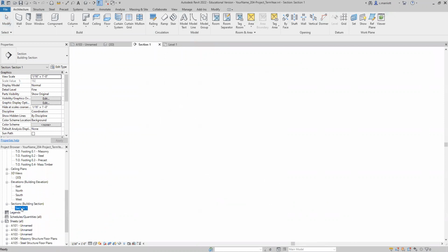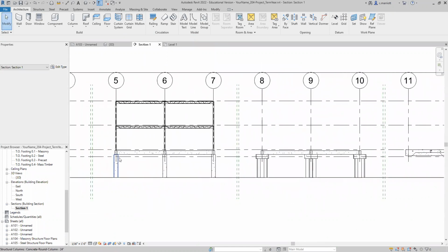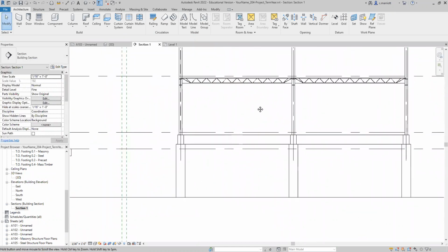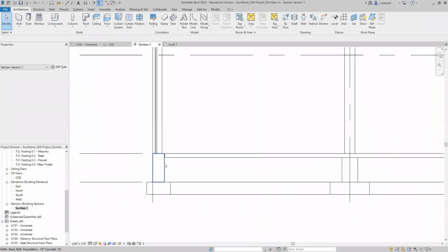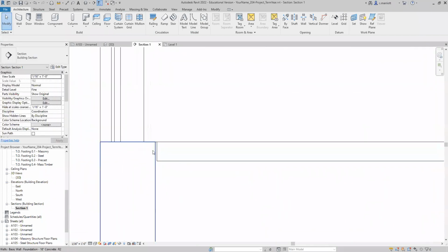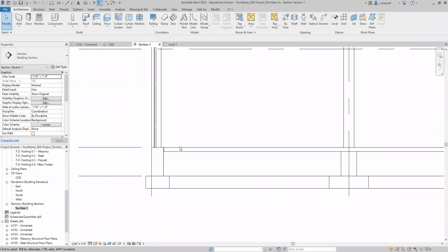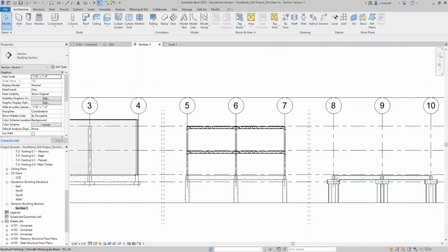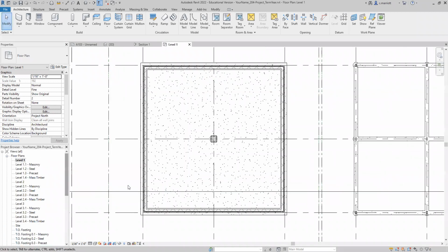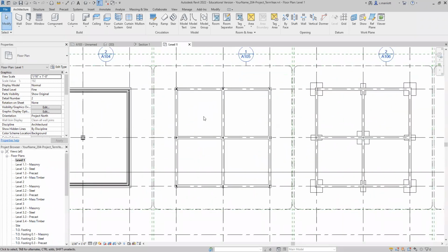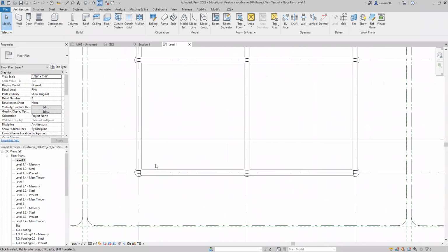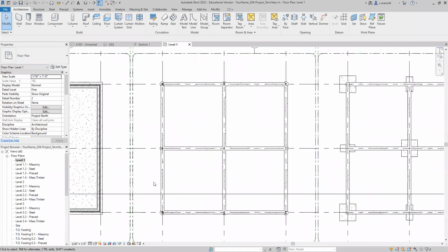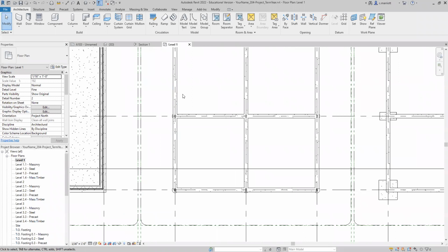I'm going to go down to the section view and take a look. Oops, not this one, for the cavity wall. So there you can see we have the concrete slab sitting 1/2 inch in from the foundation wall. Right? And we can go ahead and add a couple of concrete slabs on top of these structures that have grade beams. So I'm going to go back to level 1, go over to where I have the steel structure, and make a slab on top of this.